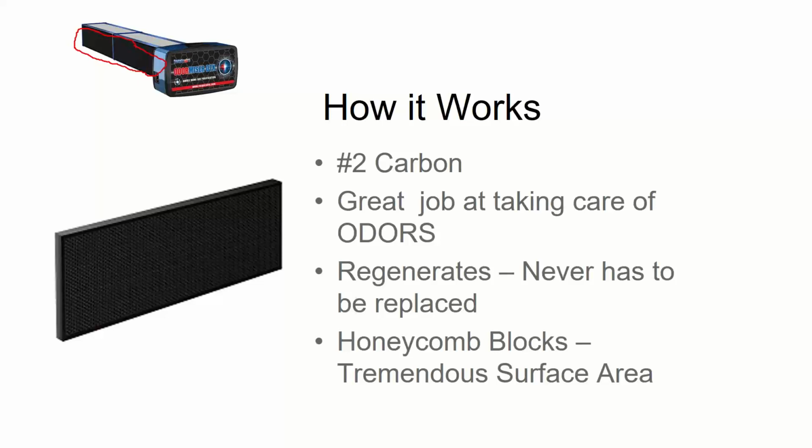Some of you that have done commercial applications may have put carbon filtration on something. There was an air handler at one of the hospitals on the south side where the intake for the air handler was next to the helipad. So 2-3 times a day, a helicopter sat there for 15 minutes spewing diesel fumes into the air that was getting sucked into the outside air intake. They put carbon filters on there to absorb those diesel fumes to help out with that situation. Apparently that was easier than relocating the intake.